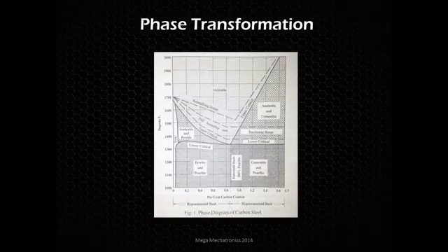So looking at some phase transformation diagrams, this will give engineers an idea of where to start with what temperature. And this is carbon content versus temperature for a carbon steel. So you see the different crystal structures within this chart that can be achieved at different carbon contents versus temperature: austenite, ferrite, pearlite, cementite, and there are other ways to even get bainite with some other post-heat treatments.